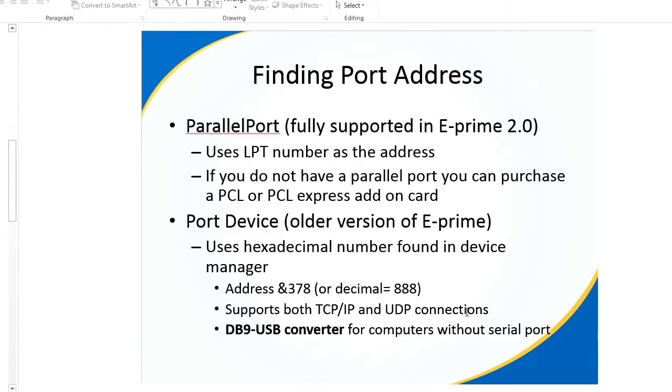In the production release of ePrime, you can actually add the socket device now, basically using the Ethernet port, to your experiment via the Devices tab, which we're going to talk a little bit about later. You open up the Devices tab under the Experiment Object's properties, and then you can add it that way. Adding the socket device on the experiment object allows you to specify the settings for the socket device right there in the experiment object. So it's pretty easy to do that.